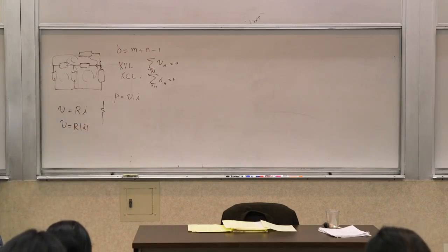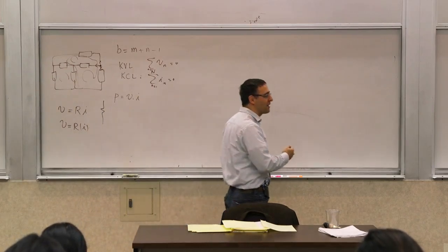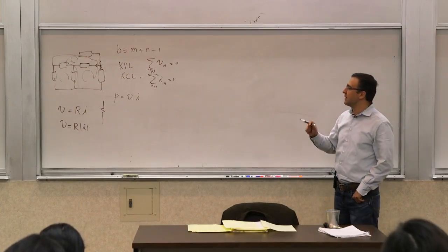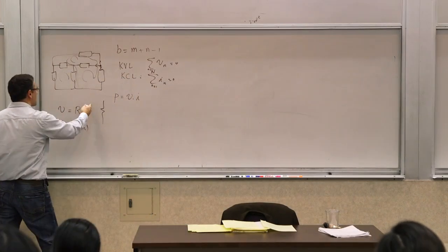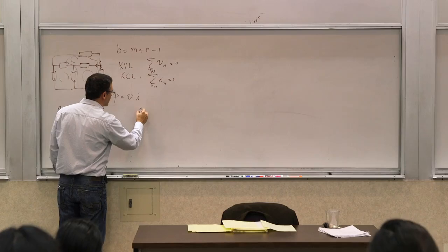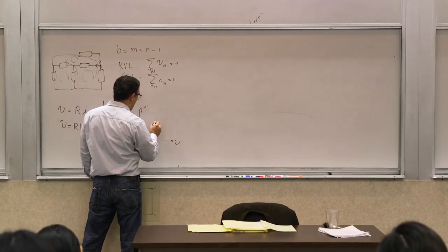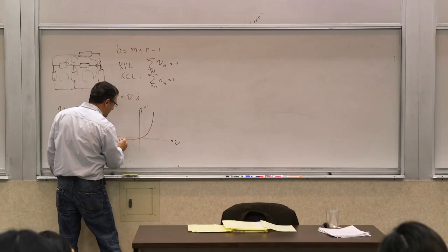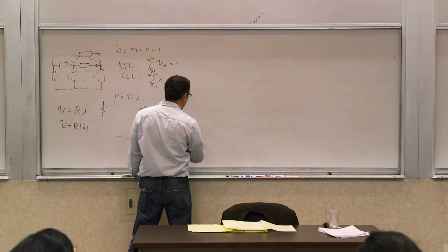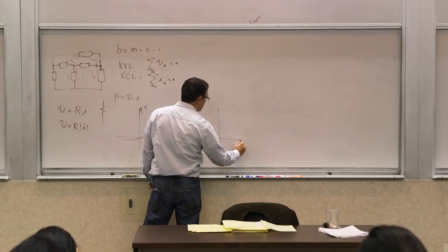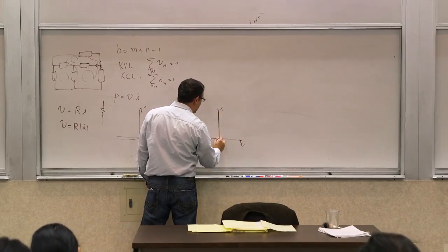And this is a nonlinear resistor. You can have nonlinear resistors, time-varying resistors, things that change, and things with memory or less memory. A memory resistor is kind of a funny thing, but most of the time it's about linearity or nonlinearity. An example of a nonlinear resistor was a p-n junction diode, which had a behavior like this. It's an exponential behavior. And we approximated that with an idealized diode, where the IV characteristic looked like that.